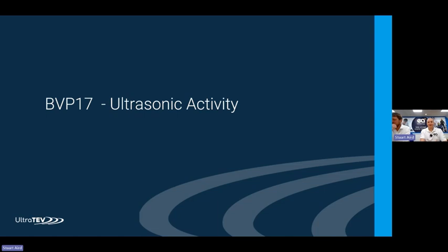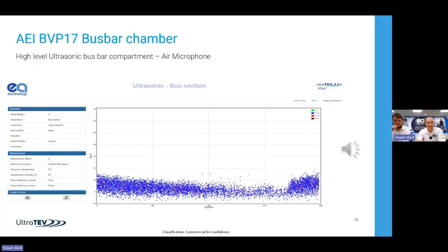Okay, so now I've got another couple of case studies on bus bars, which is another section that was mentioned at the start as not very often having partial discharge, because they don't move much. They're put in on day one and they should be all fine. But we have seen a couple of cases of those in the last 12 or 18 months.